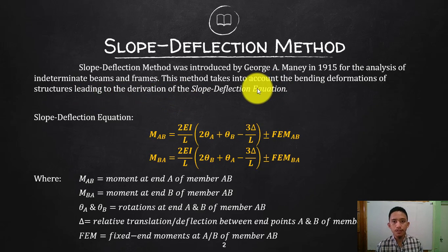Okay, so in your slope deflection method, we will be focusing on utilizing your derived equation, which is what we call the slope deflection equation, which is this one given below. Okay, so that is your slope deflection. In your consistent deformation, we are trying to release your redundant or your excess restraints, and then solving that one before solving for the rest, and then completely analyzing your structure.